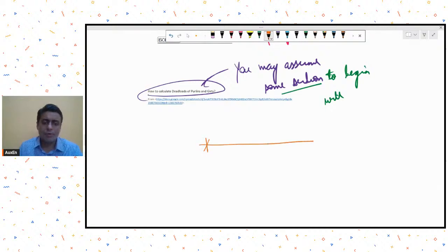For example, for normal wind load cases, up to a span of 7.5 meters, maybe a Z purlin of around 2 mm thickness, around 200 mm deep, with flange around 50 mm, lip around 15 mm, and 2 mm thick. Just hold on, give me a minute. This type of section is usually sufficient. Just hold on, I'll be back.